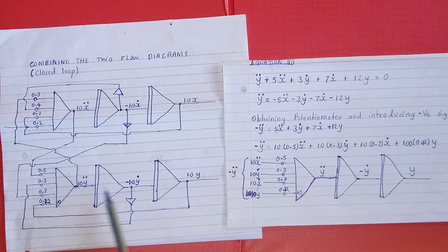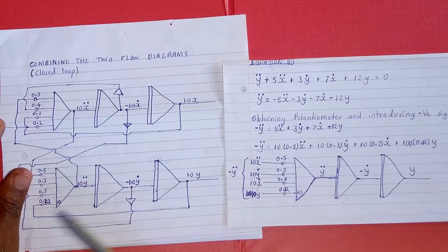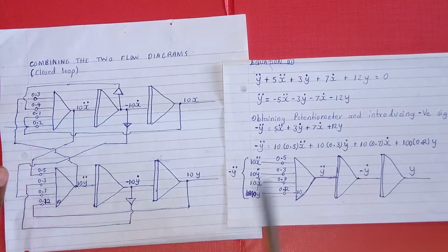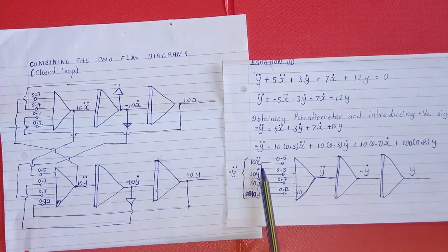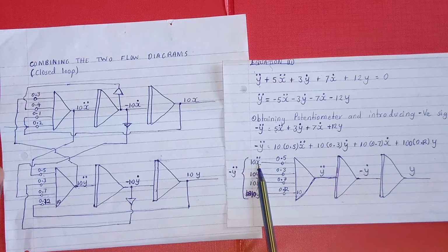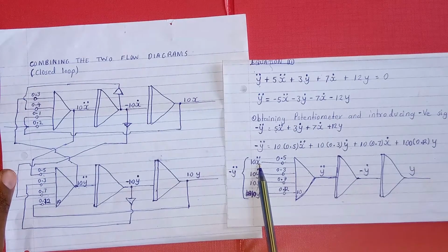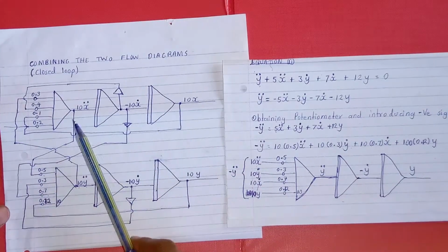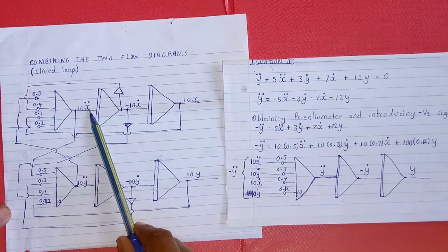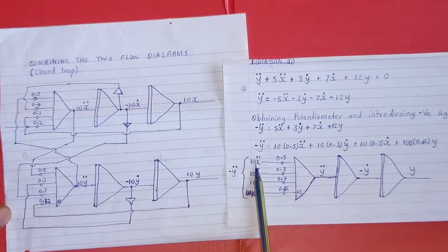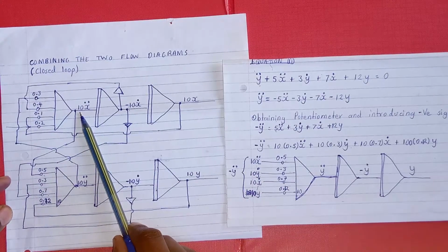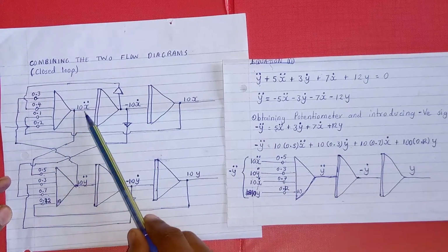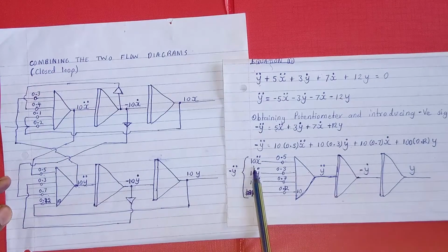this block diagram. For example, let us start with this one, which has a gain of 0.5, and its factor is 10 second derivative of x. So where do we have our second derivative of x at the combined block diagram? So here it is, second derivative of x, and the values here should be the values here. Okay, so we are going to loop here like that to that point and put a 10 here, because this value here is also 10.